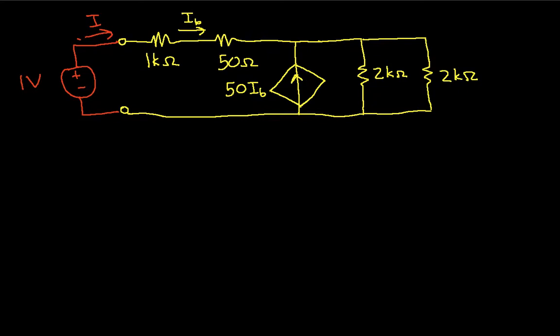And my Thevenin equivalent resistance will be the 1 volt divided by this current. Again, just to make sure it's clear, the Thevenin equivalent circuit, since I have no independent sources, is just going to be a single resistor. So all we need to do is figure out what the current is when I apply this 1 volt source. Seems like it should be fairly easy, but we'll see how it goes.